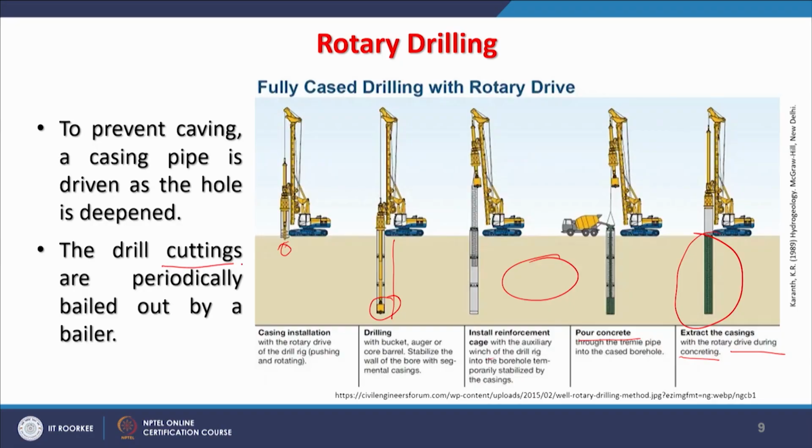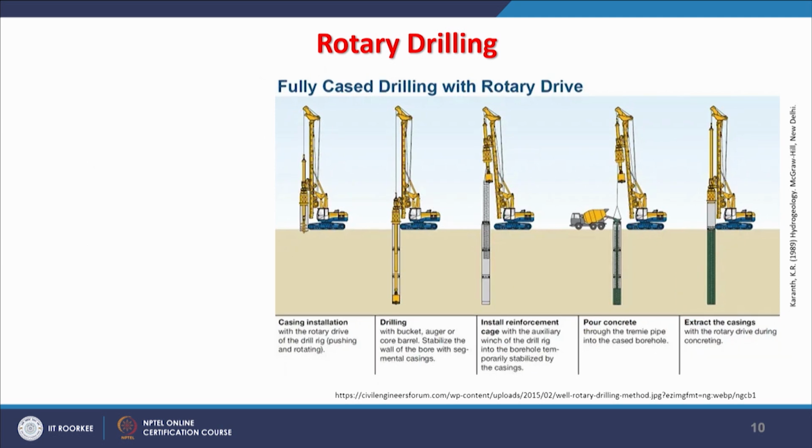So, the drilling cuttings, the material which comes up, are periodically bailed out by a bailer. That means it is collected and put in a sequence, so that we know at what depth what kind of rocks or formations were found.